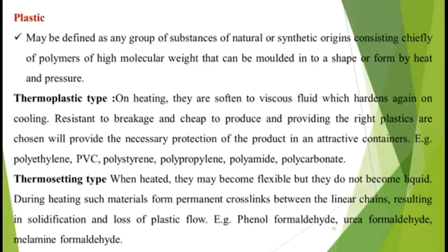Tin is alloyed with 0.5% copper for stiffening when lead is used, and 3% antimony is added to increase the hardness of the collapsible tubes. Tin is the preferred metal for food packaging.